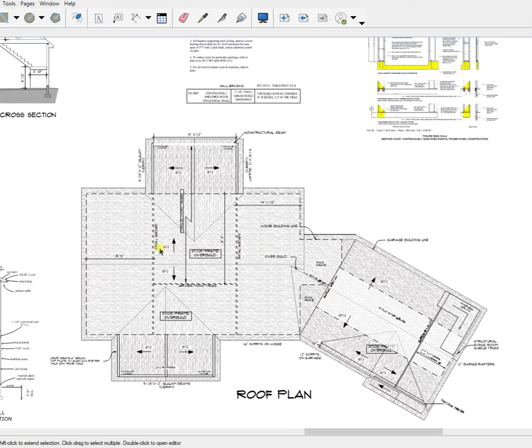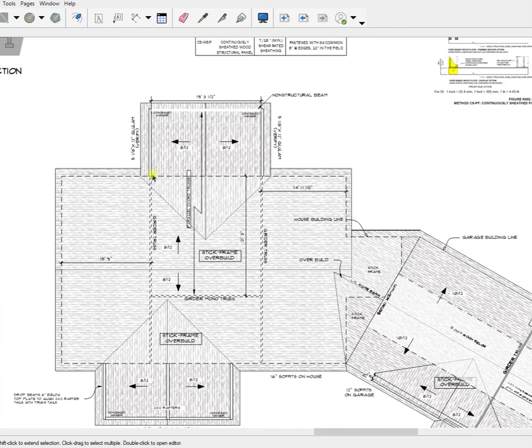Okay, now lastly, every girder truss is carrying a big load. A girder truss means that it's carrying other trusses, or floor system or something. A carrier truss is another name for it. But you know, with those laying on the wall, they're going to need pads. So this house is going to need one here, here, here, here, and then you also have a girder truss here. So here and here, and the only way you can know what that is.